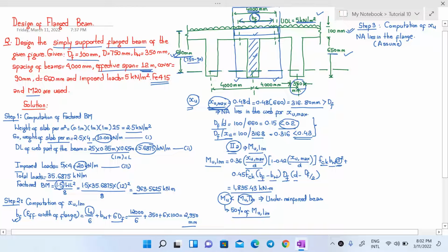So in that case, when we consider a normal rectangular beam, we can use the value of Mu as 0.87 fy Ast d (1 minus Ast fy over fck bd). We have used this formula because we assume that the steel in our cross section is allowed to reach the design stress of 0.87 fy. So all of the factors are known here except the value of Ast.